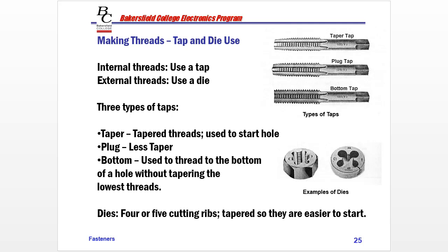So we would use a tap, for example, when we're making a part of a machine or a bracket and we want to be able to screw a bolt in it, thread a fastener into the hole. A lot of times when we're machining this piece of metal, we'll actually have the machine cut the threads. But if we buy a piece of metal that we need to cut threads into, we would use a chart, and it would usually come with the tap and die set.